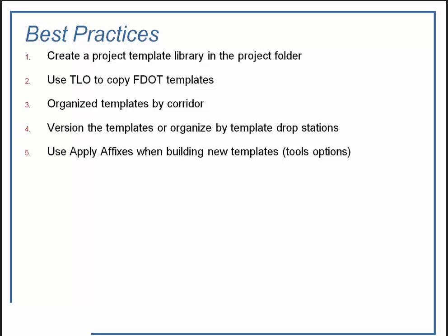Or the first time you get a zipper corridor, and a lot of you are laughing, but you know what I'm talking about. The first time you see a corridor that zips back and forth like a zipper, you're going to know that you have the same point name or point name override on either side of your template. And that's because you weren't paying attention or using the affixes when you created your template, when you were dragging in things.